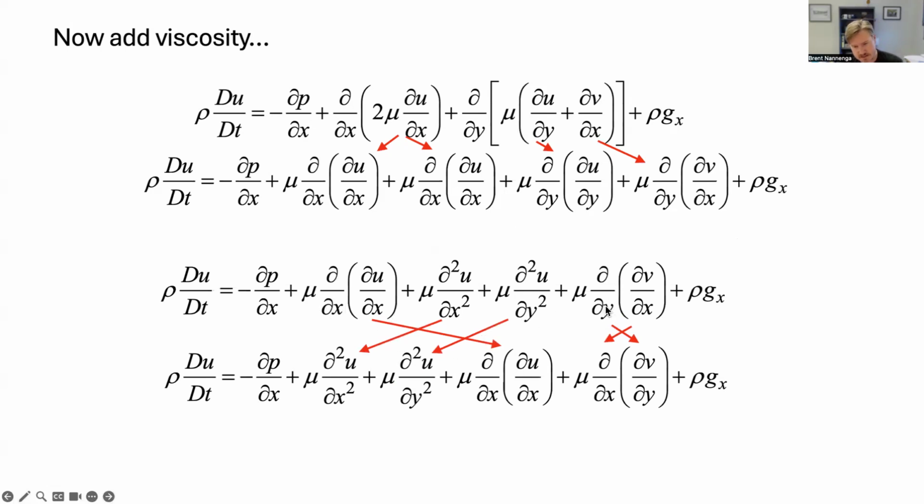And we're going to take this equation here. Instead of saying partial with respect to y times the y velocity with respect to x, we're going to swap these. And we're going to say now it's partial with respect to x, and we're going to have velocity in the y direction with respect to y. We're just swapping these two right here. So again, we're just grouping things.